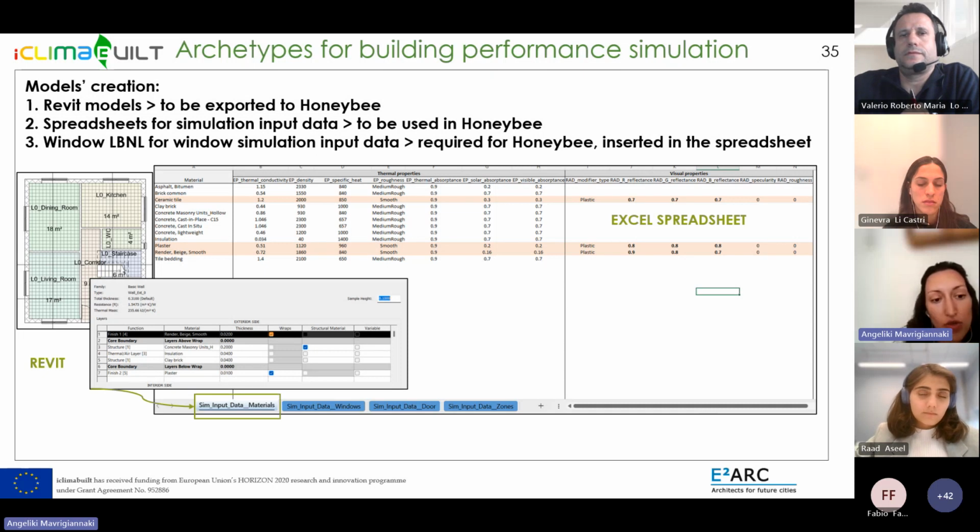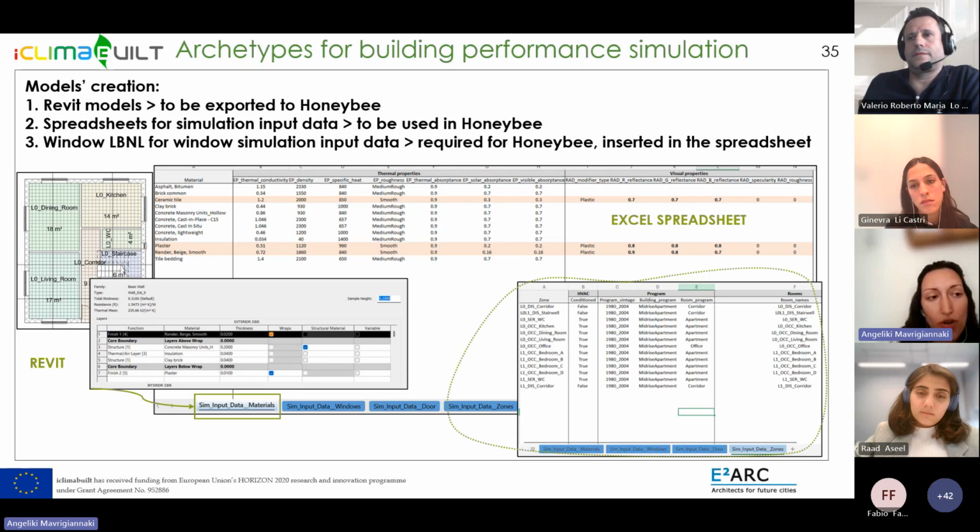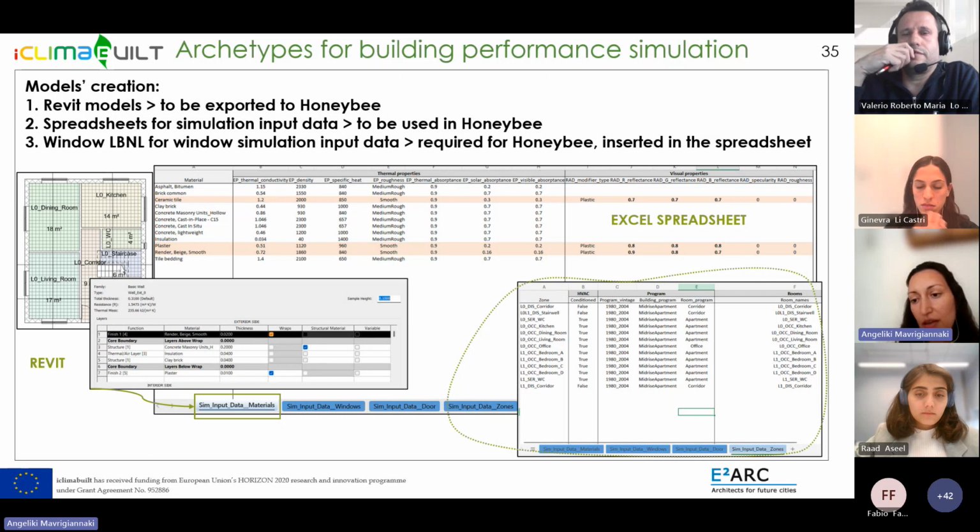And this was not only done for the materials, but also for the rooms that represent the specific thermal zones that will be used for simulation, and information about the building program and program vintage, which are representations of the occupancy and settings of each room and thermal zone to be considered for simulation.